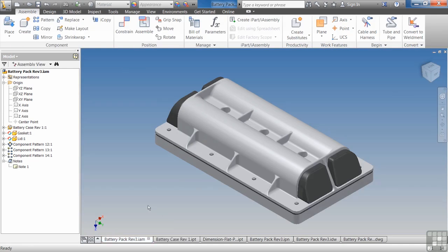You make up multiple parts, come in here to this assembly. You can see as I hover around the different parts in the assembly, it automatically highlights those and tells me, hey, that I'm in an assembly environment. You don't really care about the individual features. So when you are editing a feature in Inventor, you're at the part level. So think about it just like you would work on a real manufactured part. If I manufacture this, I'm not going to be machining out these holes after I put it together. I'm going to do it once it's all together.